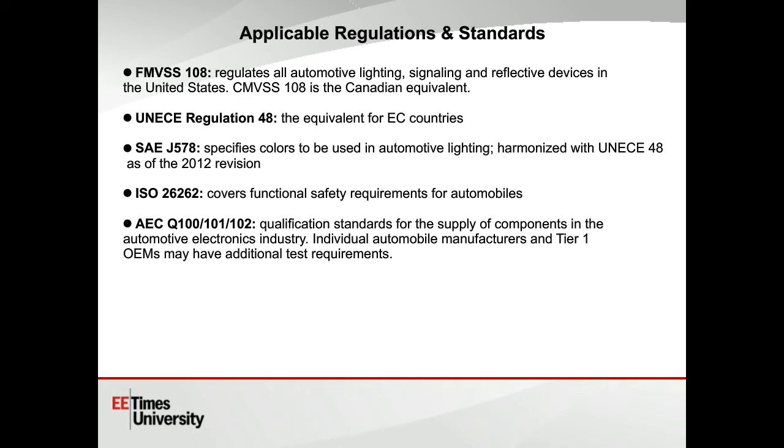Finally, the Automotive Electronics Council, AEC, has issued the Q100, 101, and 102 standards, and these pertain to the manufacturing of integrated circuits and other components that are used in the automotive electronics industry. And what we find in the industry, Toyota, GM, Audi, and so on, plus the Tier 1 OEMs, may also add additional test requirements to their products in addition to satisfying these AEC specifications.